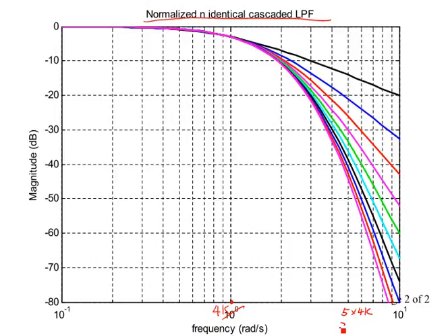After we scale that by multiplying with 4 kilohertz, it's 20 kilohertz. So at 20 kilohertz, we want the gain of the circuit to be at least 30 decibel below the passband gain. So let's look at, so here's at 20 kilohertz.